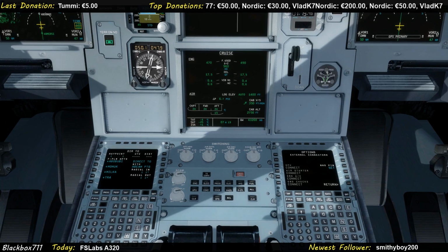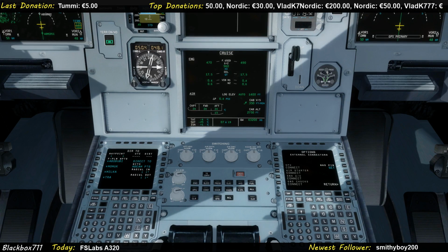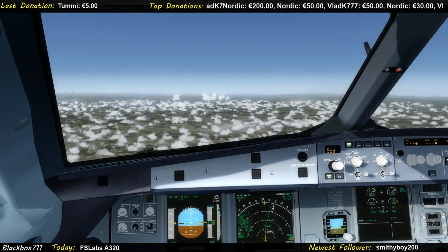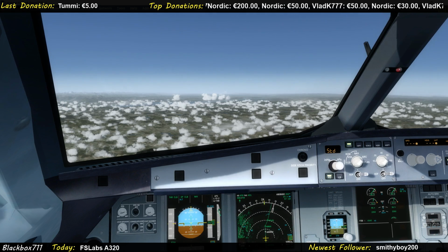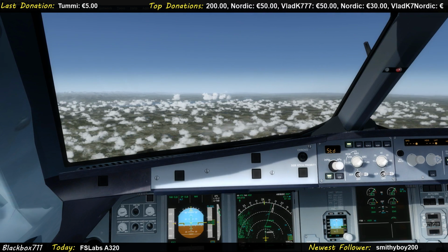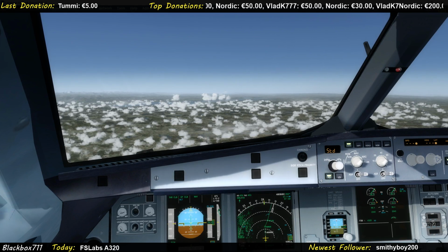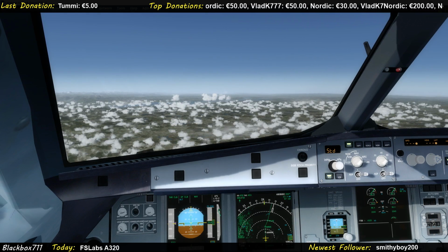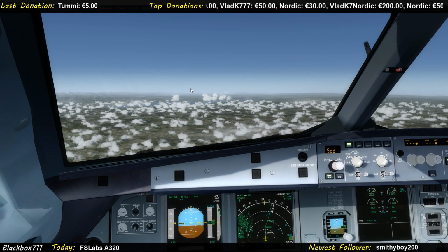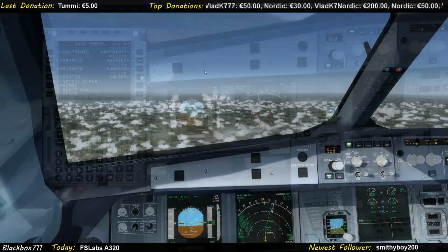What would you turn off? Would you turn off the passenger signs right after 10,000 feet, or wait if there are any turns shortly? Yes, your cabin crew will thank you if they don't get up and pull out the trolleys while you're doing a 30-degree bank. So you pull what, 1.3, 1.4 G in a 30-degree bank, so don't do that, yeah. Also, of course, you would have a look and make sure that you don't have any big clouds around. You know, you're sure there's no turbulence reported before you switch off the seatbelt signs. Definitely.